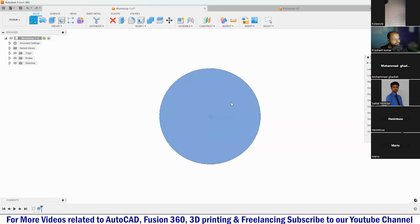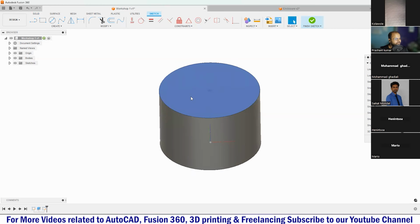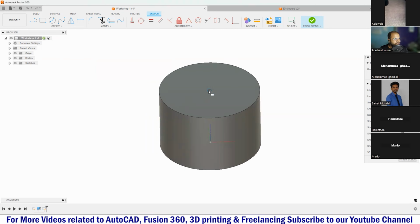Here you can see, the moment I selected the top plane as a sketch plane, we are in the top plane, ready to create a sketch. Now this plane is acting as a paper. Now I can create my sketch. This time I will go to the create panel, to the rectangle tool, the center rectangle tool. I will activate my center rectangle tool, select the center, and create a rectangle like this.